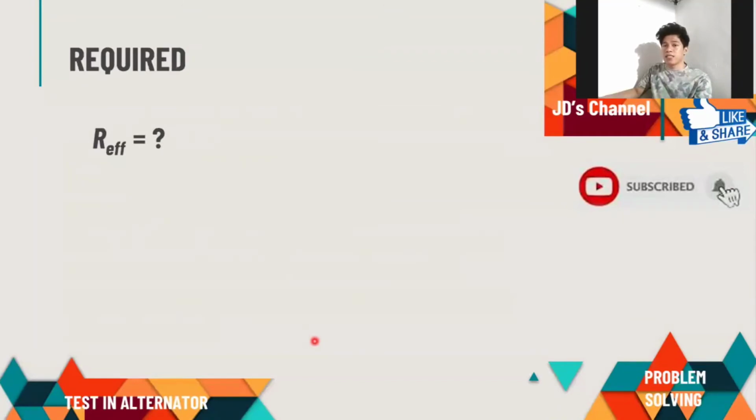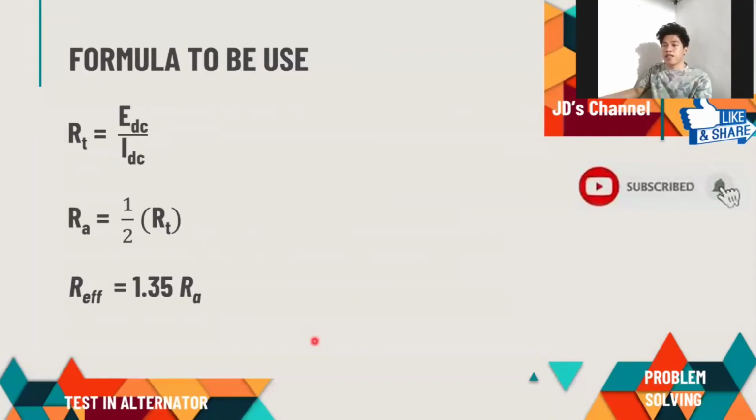effective resistance. And the formula to be used: first we will get the RT, or the terminal resistance, that is EDC over IDC, and getting the RA, that is 1/2 of our RT.